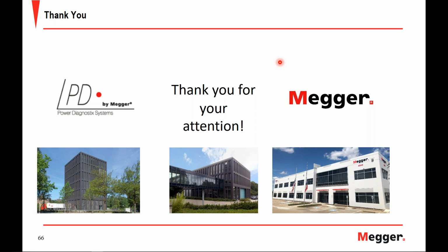All right, thank you. Jeroen, can we use VLF test sets for PD measurements? Yeah, that's a good subject. So very low frequency is a well-known test technique for cable testing. Medium voltage cable tests actually fit perfectly with the previous question we had. Our ICMflex and the ICM system are able to synchronize on VLF frequencies. So basically the equipment is prepared to do a measurement at either power frequency or VLF frequencies. The only thing that should be considered, and I luckily made my thesis about that a couple of years ago, is that there are significant differences between a very low frequency sine wave and a power frequency sine wave in terms of